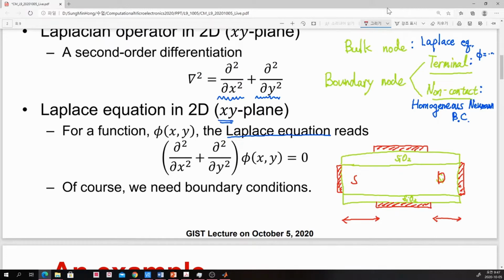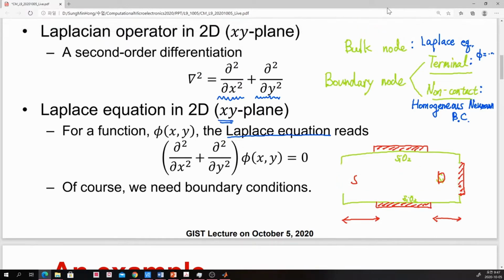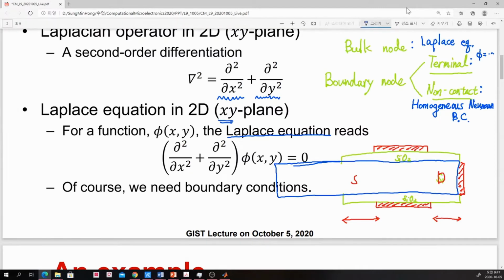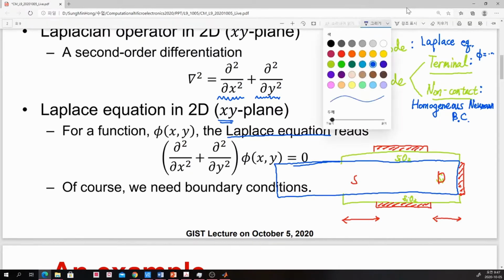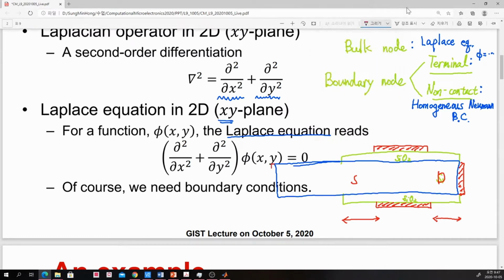The best way from the viewpoint of numerical quality of our solution is to set a really long structure and place your contact at the end of this long structure. Then you will find that every electric field will diminish in this highly doped region.